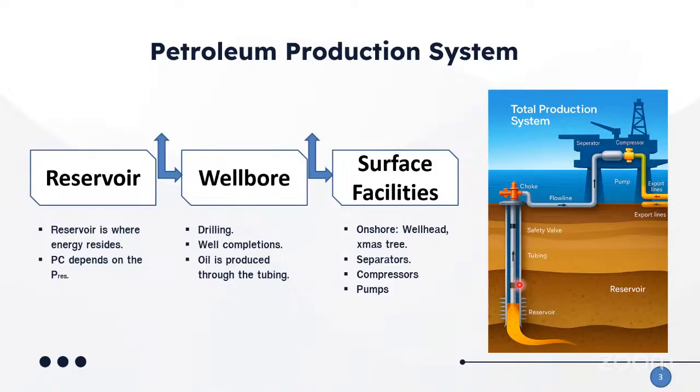The packer will be somewhere here so that all this fluid coming in will be confined into this space and be pushed within this tubing, because we want to produce through tubing. Then this safety valve is a means of emergency. During drilling, we have a blowout preventer. So during completion and production, we begin this safety measure through the subsurface safety valve. It can be tubing retrievable, it can be of any type.